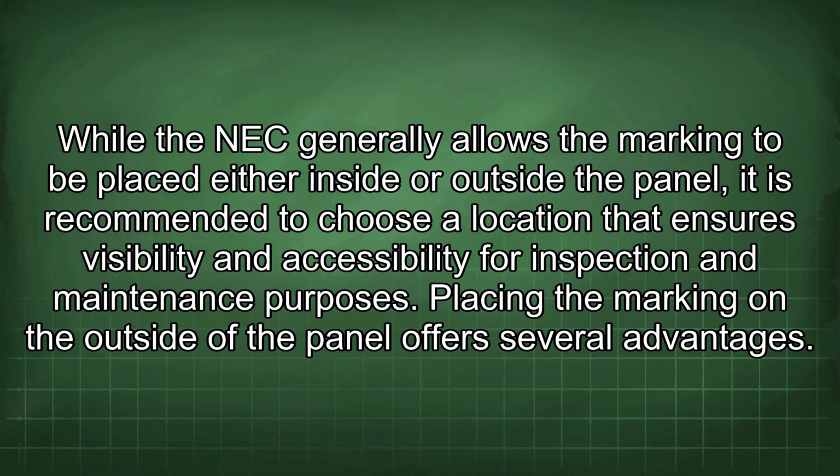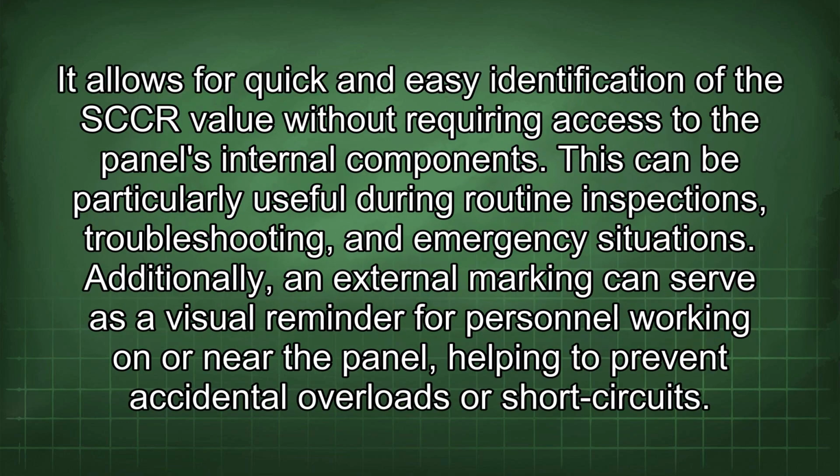Placing the marking on the outside of the panel offers several advantages. It allows for quick and easy identification of the SCCR value without requiring access to the panel's internal components. This can be particularly useful during routine inspections, troubleshooting, and emergency situations. Additionally, an external marking can serve as a visual reminder for personnel working on or near the panel, helping to prevent accidental overloads or short circuits.